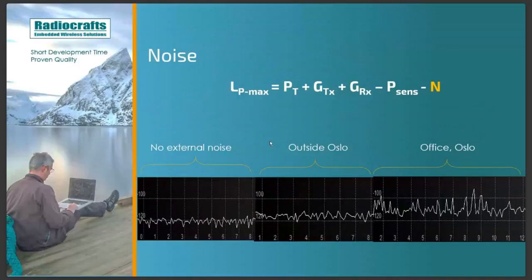If you look at the noise spectrum on the right side, between 8 and 9 seconds, you see the noise is varying very much. If we were doing LPWAN, like LoRaWAN or Sigfox, the packet lengths are more than 1 second. So a long packet will certainly get many of these noise spikes in it, while a short packet of a couple of milliseconds or 10 milliseconds could hit these low noise time slots.